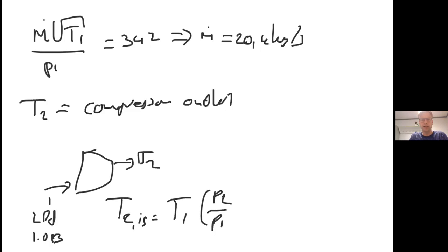I share the screen. I lost my whiteboard again. If you look at the compressor diagram, on the dimensionless mass flow, if you have the pressure ratio of 4, you can read in the compressor diagram that the isentropic efficiency is 75%, and the dimensionless mass flow is 342. I will show that again on the compressor diagram when I finish this calculation.